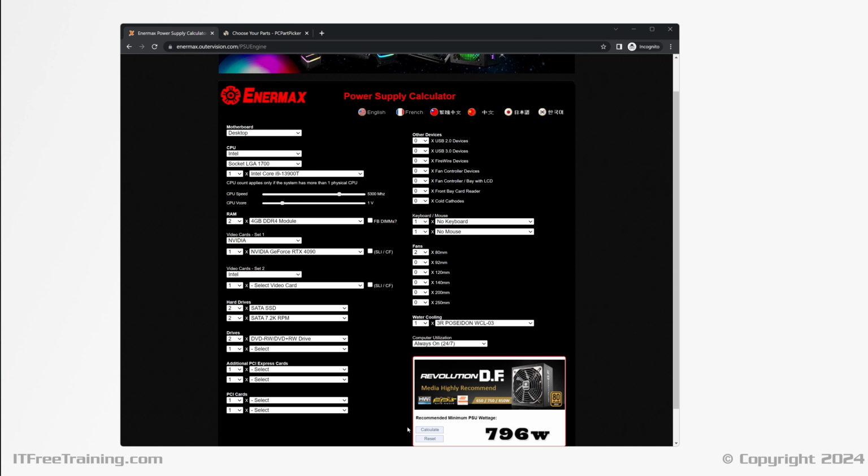The main takeaway from this is that, generally speaking, you need to estimate the power you need for the biggest power users, which will be the graphics cards followed by the CPU. Next, I'd consider the number of storage devices that you're likely to add. Although putting everything in the estimate will help give you a better estimate, getting the CPU and graphics card correct are generally the most important.